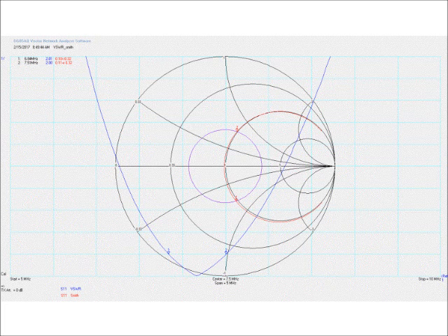So if we start here at 6.5 megahertz, remember I said if it's short, it's down in this part. This is short all the way until it gets to here. And then that's exactly resonant at exactly 50 ohms in this case. And if you go on up, the antenna is actually a little bit long, and it's still within 2 to 1, up to this upper limit, which is 7.5 megahertz. So you get to see what the SWR curve is. You can tell what's going on with the feed point impedance, and you can tell whether the antenna is too long or too short. That's what the new antenna analyzers give.